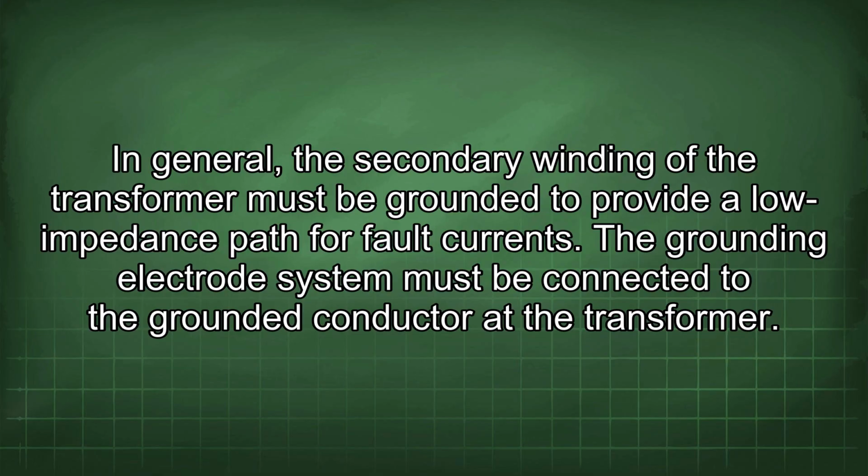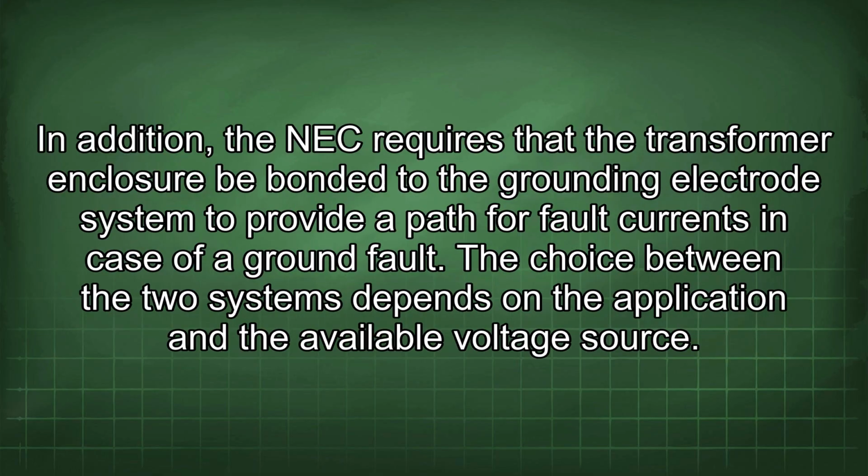The grounding electrode system must be connected to the grounded conductor at the transformer. In addition, the NEC requires that the transformer enclosure be bonded to the grounding electrode system to provide a path for fault currents in case of a ground fault.